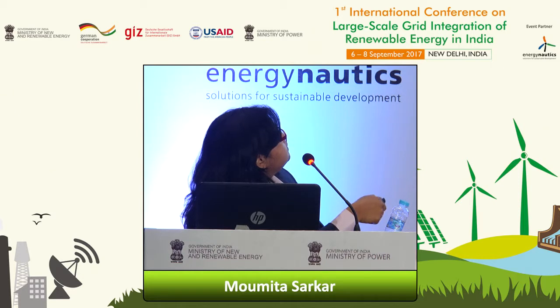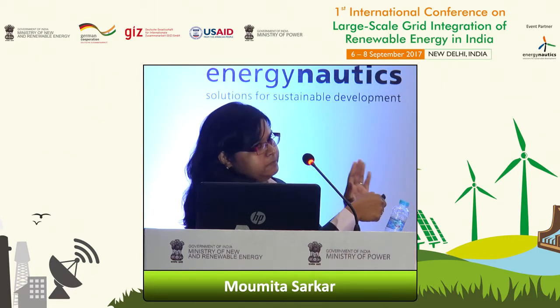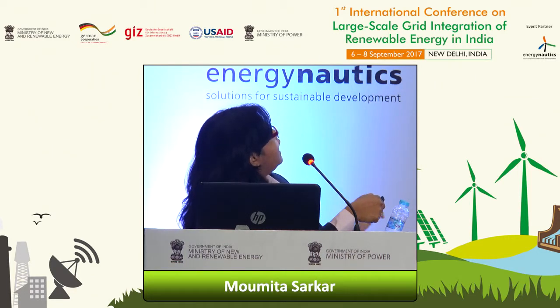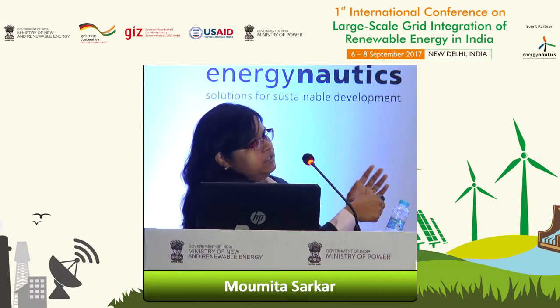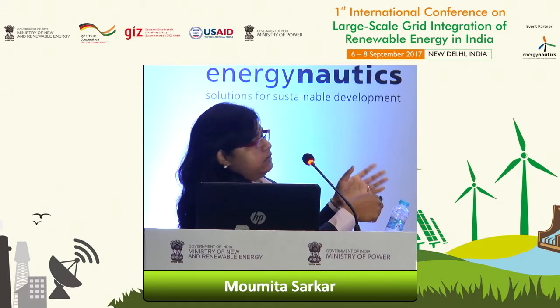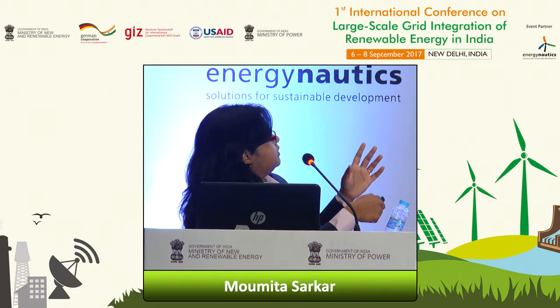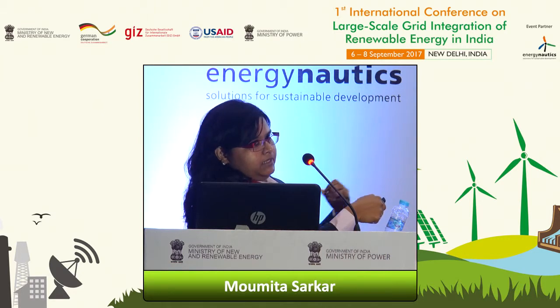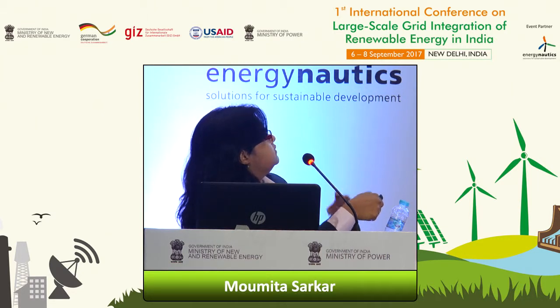When the rated wind speed is reached, the active power and the generator speed become constant. But now the pitch control mechanism comes into action and the pitch angle starts to increase so as to limit the rotor output such that the generator remains within its speed limit.